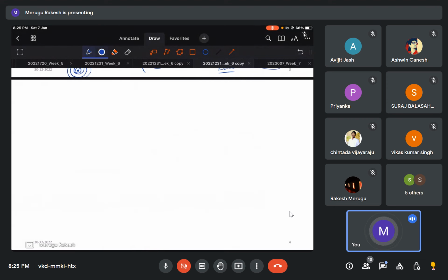It measures only one value, whereas the go gauge measures multiple values. Like I said, you can measure the roundness, the ovality, as well as the dimension. So more parameters are involved in the go gauge. That was just an explanation. If you can find a better explanation, you can let me know in the next class. So go gauge controls more parameters. Yes. It's like a 3-point measurement, whereas the no go gauge is only a 1-point measurement. It just measures the dimension.